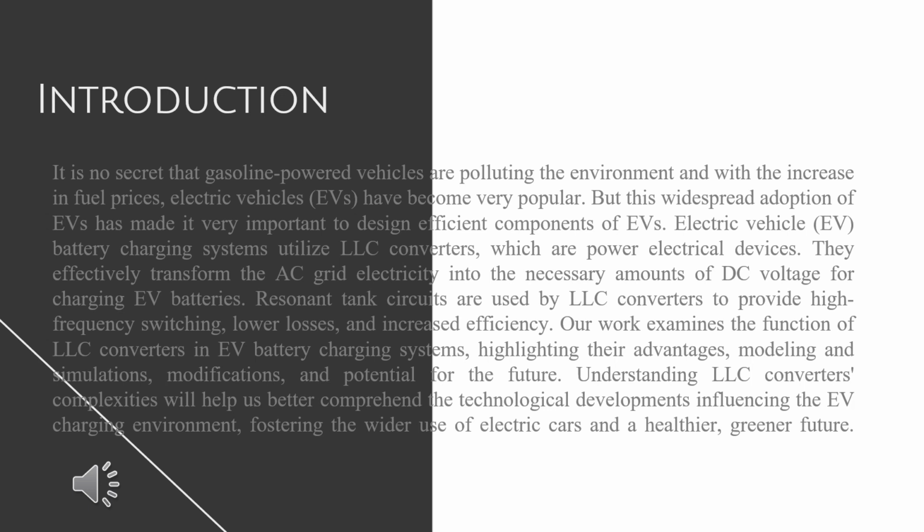Electric vehicle battery charging systems utilize LLC converters, which are power electrical devices. They efficiently transform the AC grid electricity into the necessary amounts of DC voltage for charging EV batteries. Resonant tank circuits are used by LLC converters to provide high frequency switching, lower losses, and increased efficiency.